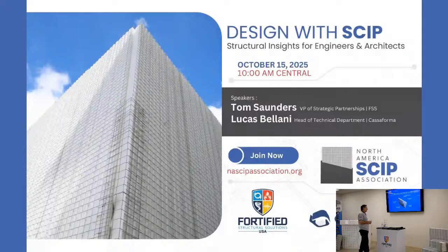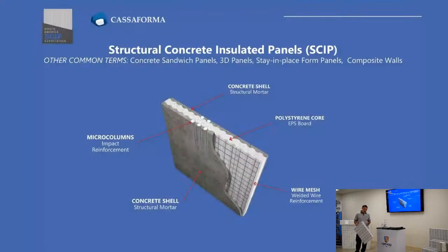Well, the first thing that we have to understand is the concept of the way the panel works. As it's here on the slides, we can see that basically it's like a concrete structure. The difference is that it's a lightened one. Why? Because the core is made of EPS, so that means the core weighs almost nothing, and it provides a place to run all the facilities that we need, and basically all the insulation, okay?